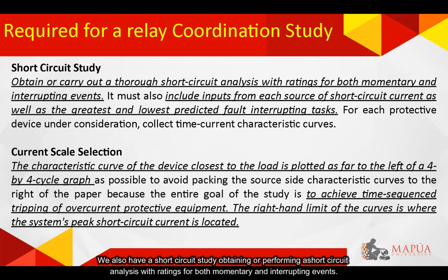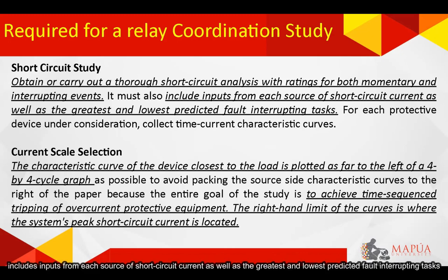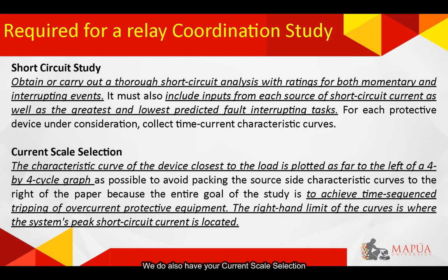We also have here the short circuit study, obtaining or performing a short circuit analysis with ratings for both momentary and interrupting duties. It includes inputs from each source of short circuit current as well as the greatest and lowest predicted fault levels. We also have current scale selection.